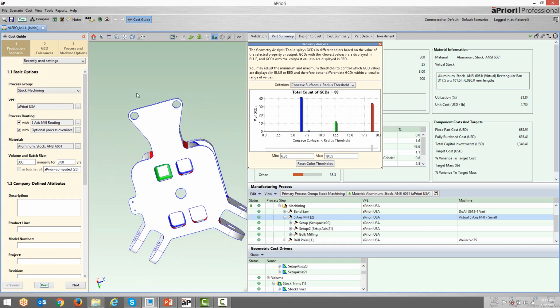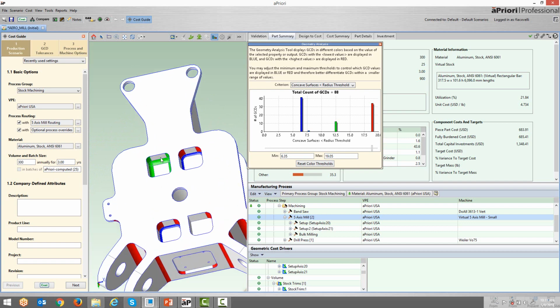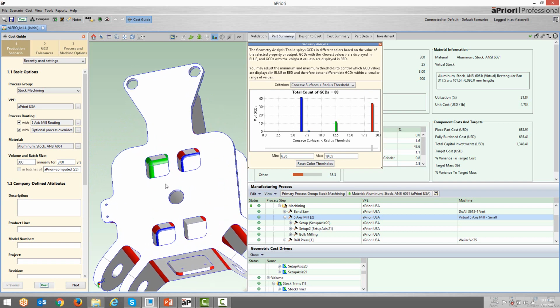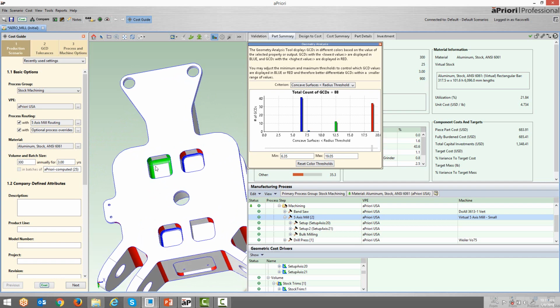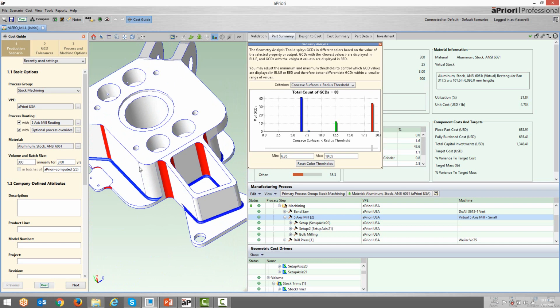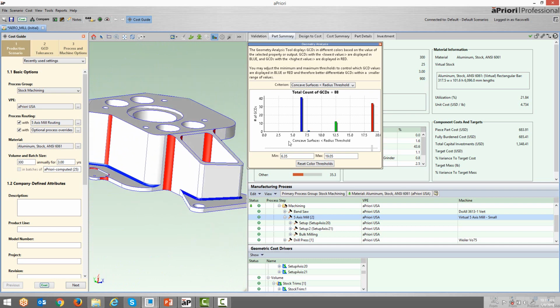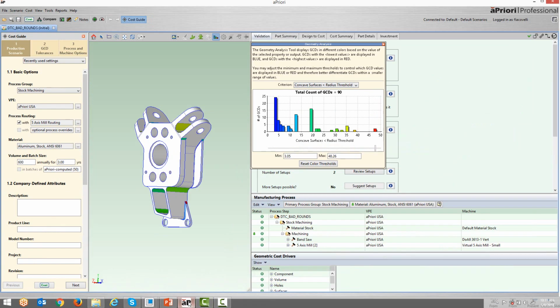And then if we flip over to the bottom of the part, you can see some other stuff here. When I see this condition, that means I have 3 radiuses coming together in one corner. This is going to cause problems for when we machine the surface because I'll have to face it and then ball mill it, and I highlight that in other areas. This is a very healthy, good-looking curved surface radius threshold analysis. I've got an example of a bad one.